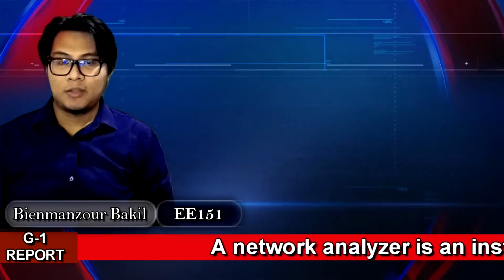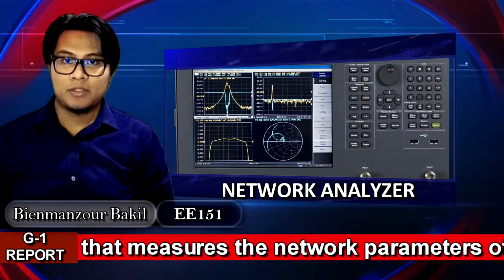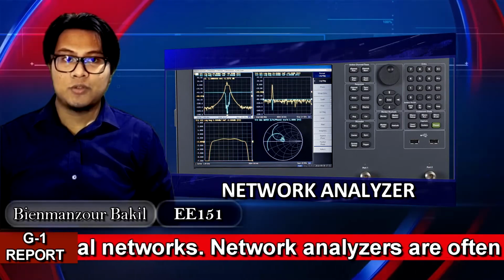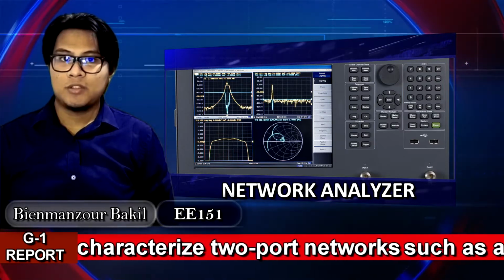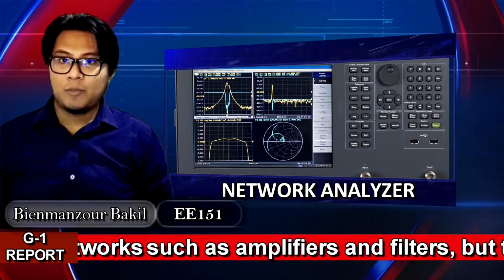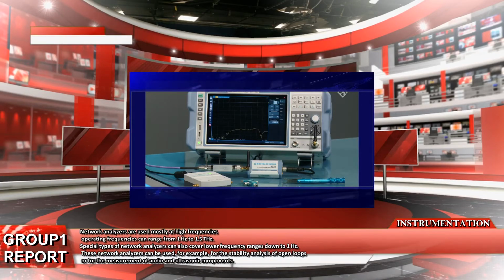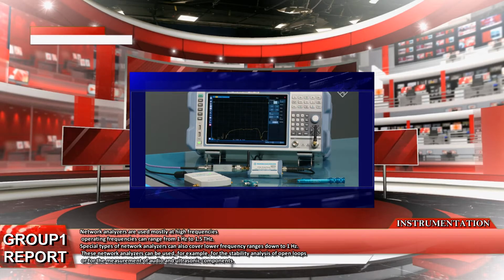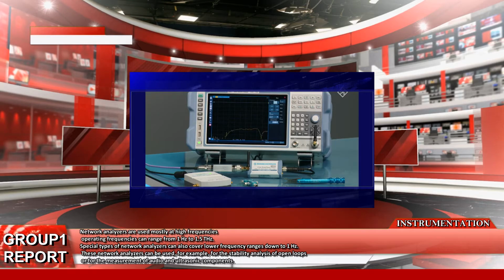Next up is the network analyzer. A network analyzer is an instrument that measures the network parameters of electrical networks. Network analyzers are often used to characterize two-port networks such as amplifiers and filters, but they can also be used on networks with an arbitrary number of ports. Network analyzers are used mostly at high frequencies. Operating frequencies can reach from 1 Hz to 1.5 THz. Special types of network analyzers can also cover lower frequency ranges up to 1 Hz.